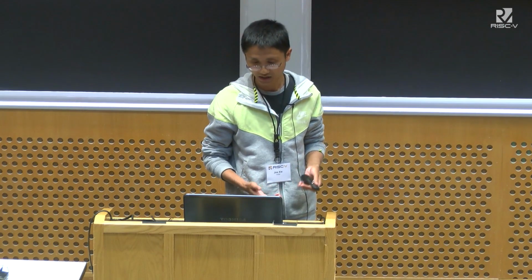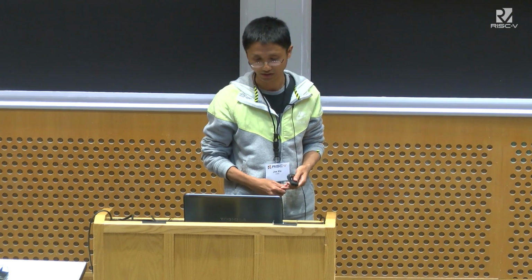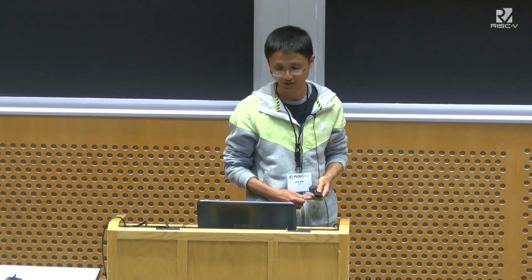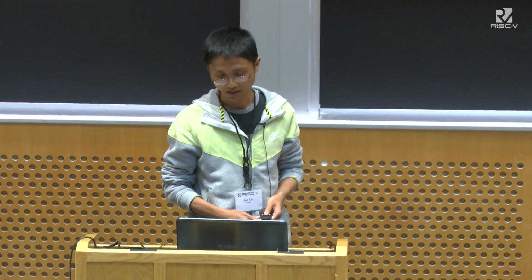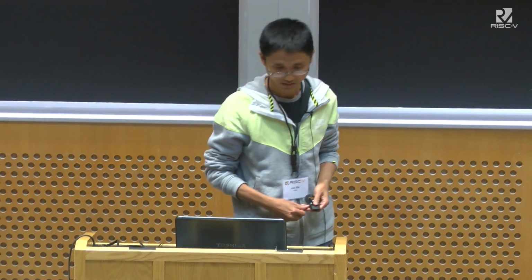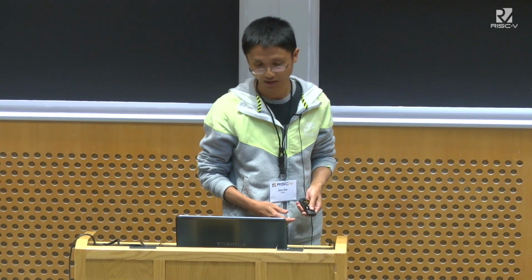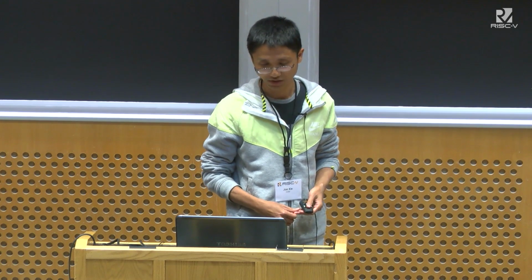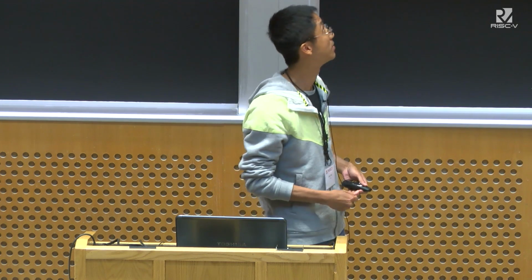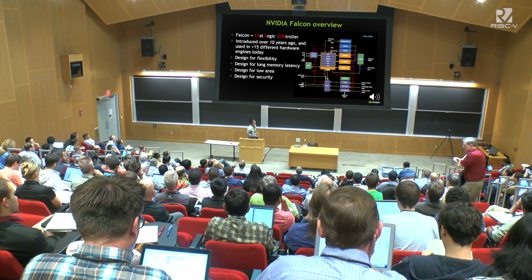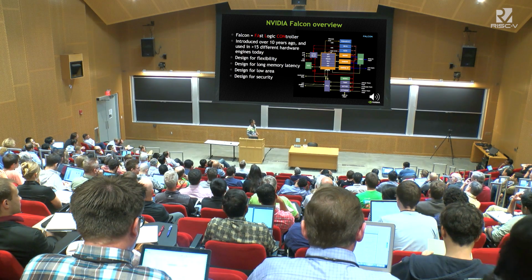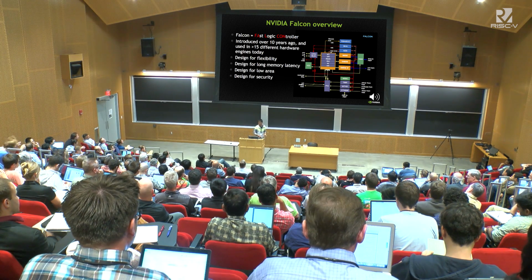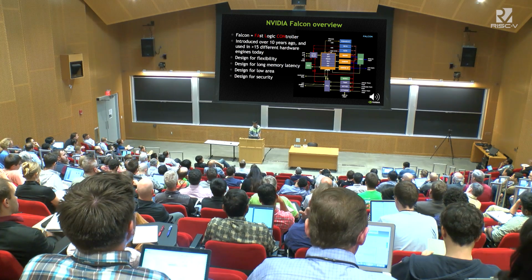The design target at that time was that, because we needed it in a lot of different hardware engines, it had to be highly configurable. Everything other than the basic pipeline can be configured, so it can fit multiple hardware engines. It also had to be designed for long memory latency, because in our GPU and Tegra SoCs, the memory latency between our hardware engine and memory is pretty long. We're talking about 500 to 1,000 cycles of latency.